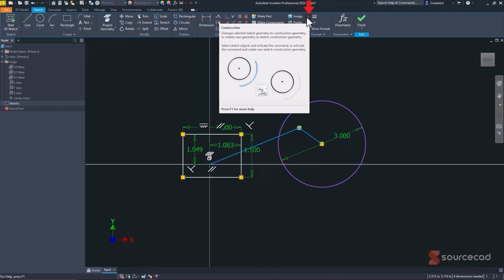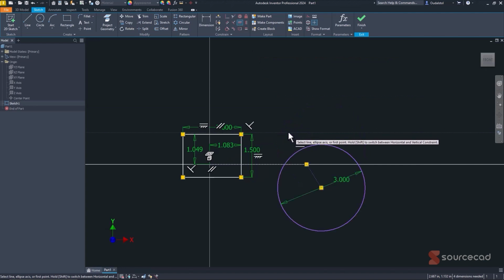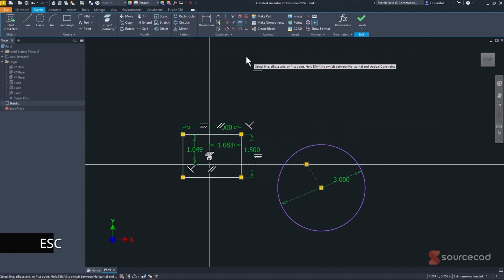It's a help line. It's just to have. I need to tie in because I'm going to dimension these, for instance. Now, I didn't want to draw it along this line right here, and I'm going to get the constraints in, right? So I'm going to make this one horizontal, which is this one right here. And notice the help line, because I want to mention, it's not always that what you're looking at is the horizontal line. So you might have to do, and again, notice the line going up and down. But in this case it is. So I'm going to say this line is horizontal. And, well, let's hit escape to get out of it.